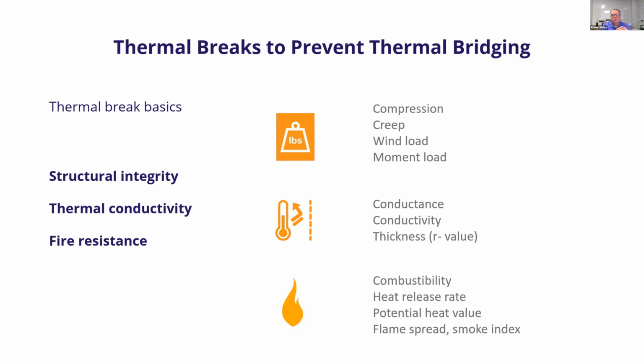The building code officials are going to start eventually looking at this hard because most thermal breaks that are on the market today are combustible technically. There are a few that are non-combustible, but how they may or may not affect the fire rating of the wall is important, right?